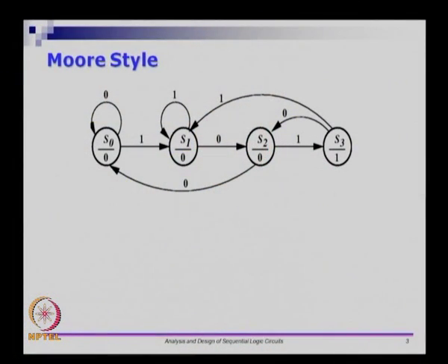So the Moore machine is essentially that. It is the same thing that I did in the picture. There is a reset state here, S0, S1, S2, S3, and S3 on a 0 goes here, or S3 on a 1 goes here. S1 and S3 both expect 0 1, except that one of them is producing 0 as the output and another one is producing 1 as the output. That is an important distinction. Because the states dictate the outputs, these two states have to be different.